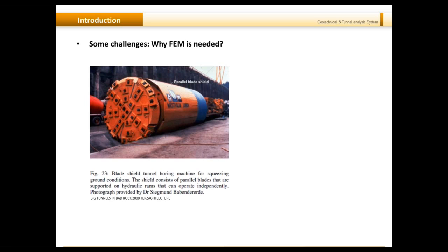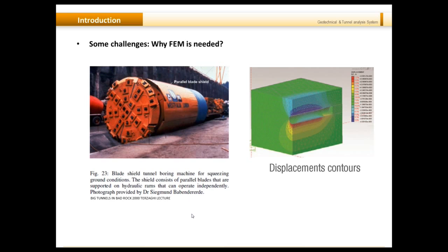If you are not digging further in the longitudinal direction, it will lock the shield in that position and the stresses around it. This increases safety, and once you start drilling, it will aid in the excavation itself because it's also rotating and clearing out the additional area.